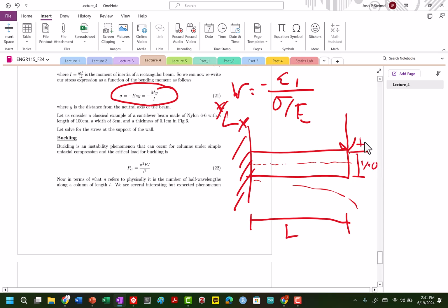So basically here it's going to be the thickness, h over 2 plus h over 2 or minus h over 2. h is typically the thickness when we look at rectangular beams, and I, which is our moment of inertia, is going to be the base, which is the width. If you could imagine the three-dimensional beam, the width in this direction, that's going to be our base. Times our height, which is the thickness here, cubed, over 12.